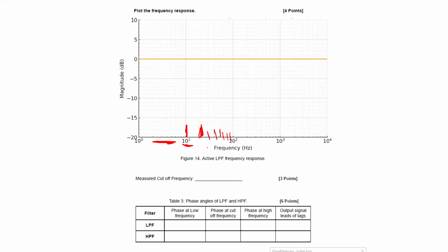Very simple. Actually, this one you multiply by 2, multiply by 3. So this one is 10, so the next lines here are 20, 30. You see what I'm saying? So between each two lines, we'll find 9 lines. This first line here, you multiply by 2, by 3, by 4, 5, until the last one, multiply by 9, and then if we multiply by 10, you will get this one here. Okay? The same thing for the other one, absolutely the same. So this one here is 1 hertz. When I multiply by 2, this is 2 hertz, right? 3 hertz, 4, right?